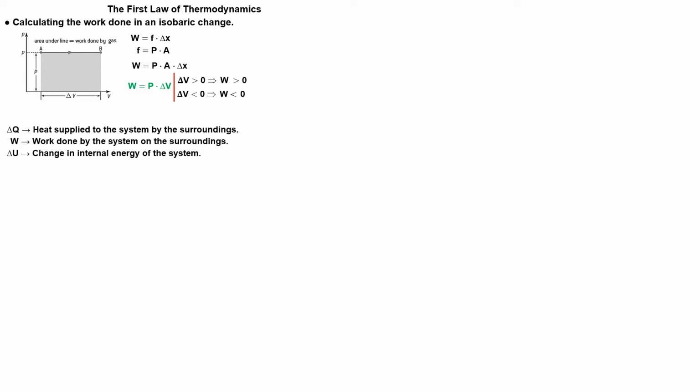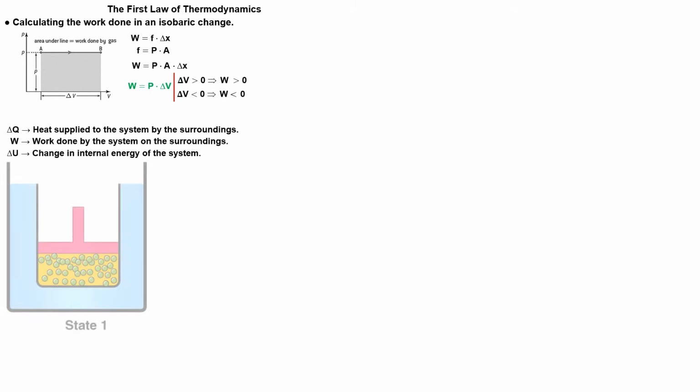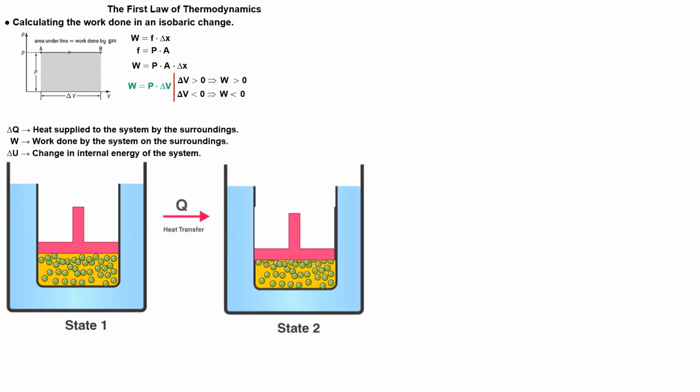Nothing quite exemplifies the first law of thermodynamics as well as a gas trapped in a container with a tightly fitting movable piston. We will assume the piston can move up and down, compressing the gas or allowing the gas to expand. When heat energy is applied to the gas, the temperature of the gas increases. Then work is done by the gas expanding to move the piston, resulting in a change in the internal energy of the gas.